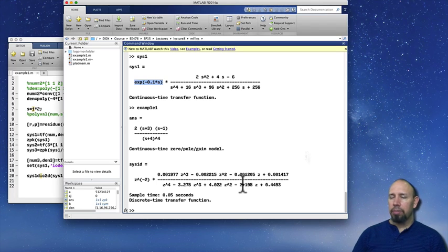But you can do the same kind of thing that we talked about. And so here it's in the z domain, and notice that because of the time delay, this time delay translates into these extra z inverse negative powers out front, which is fine. This is actually true, but generally speaking, we want these lumped in with the transfer function, and